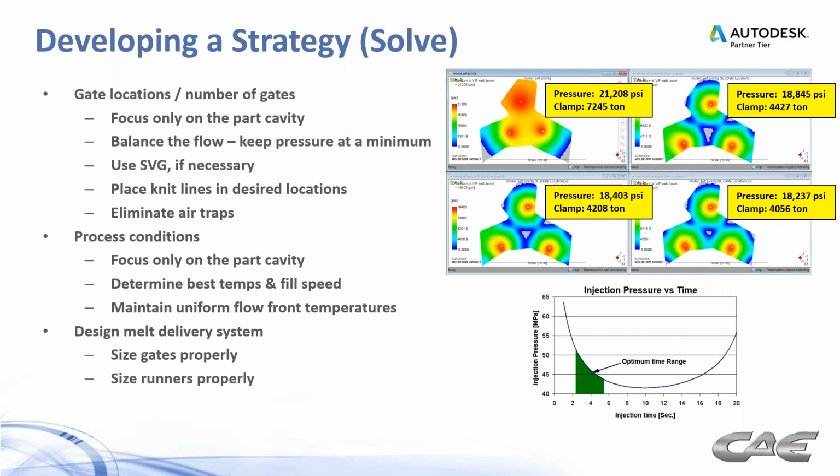And we're usually going to do that in a brand new mold without even building a runner system. We're just going to put some points on the part, as you can see on the right, and play around with different locations until we see good balance. As is the case with everything in injection molding, there are trade-offs, and you can see one of them pretty clearly on the right. Balanced gate locations with 3 gates there is going to produce an air trap in the center of the tool.